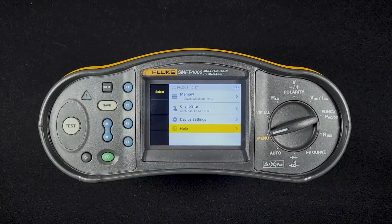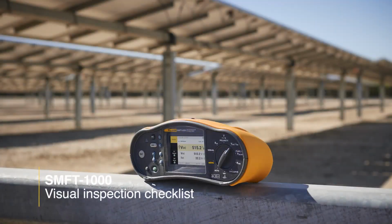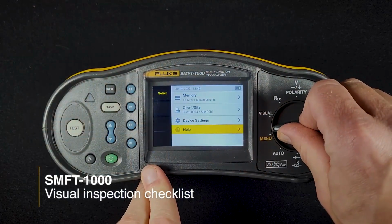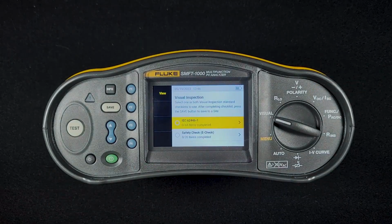That's all the information contained in the menu of the SMFT-1000. We're going to review the visual inspection checklist in the SMFT-1000. So just switch the dial to visual. In visual inspection, you have two checklists. You have one based on IEC 62446-1 with 44 different items. The other one is a safety checklist with 20 different items.